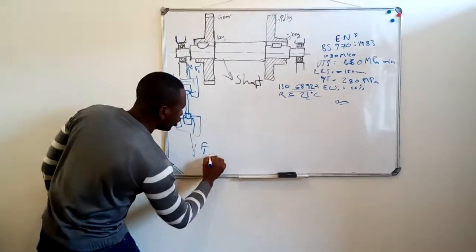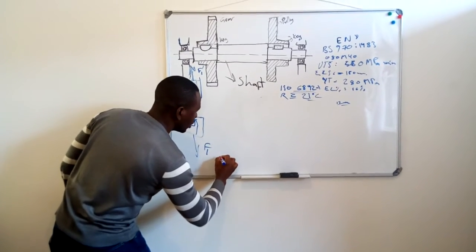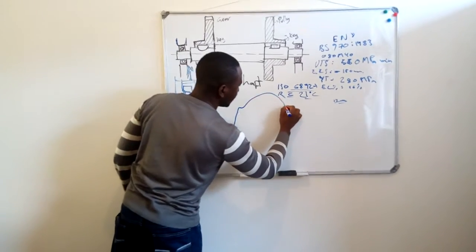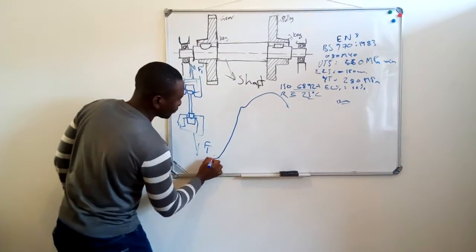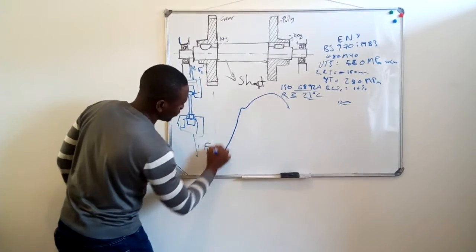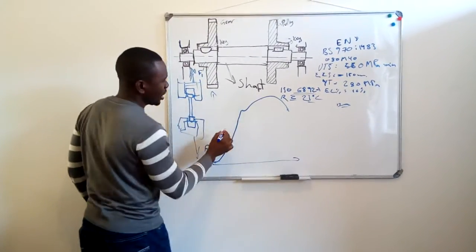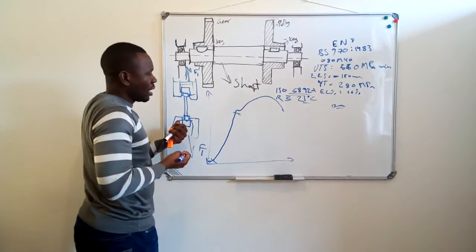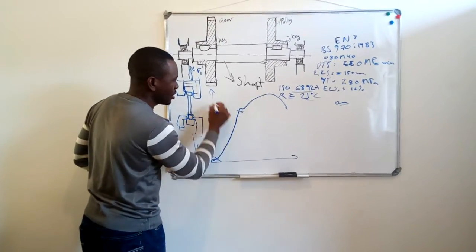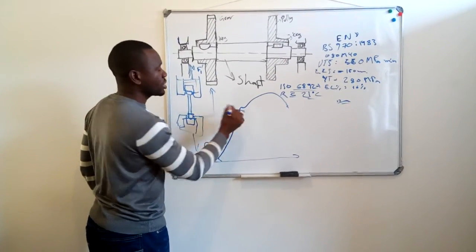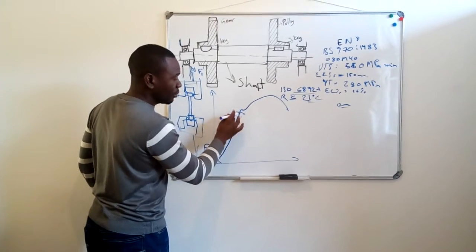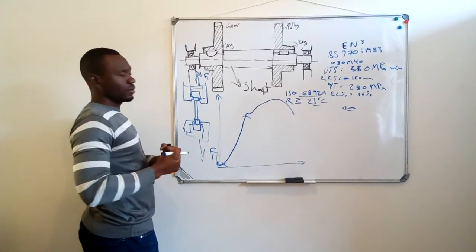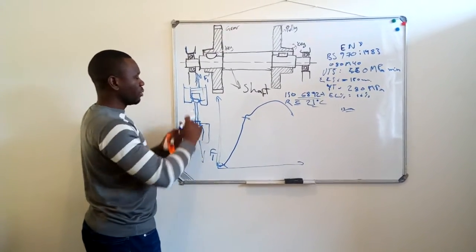So we all know the graph of the tensile test. It goes like that, and then bam, it breaks there. What you're seeing here is the zone of elasticity. When you put your sample under the machine, this zone is the zone of elasticity, which means if you remove the load while pulling, the sample can come back to its original size, both diameter and length.